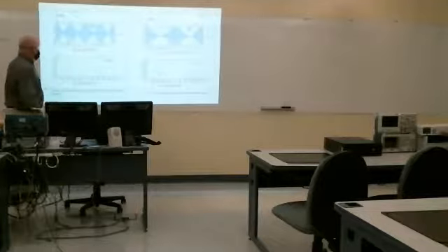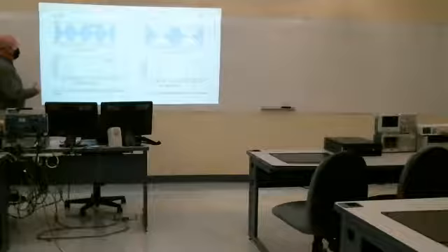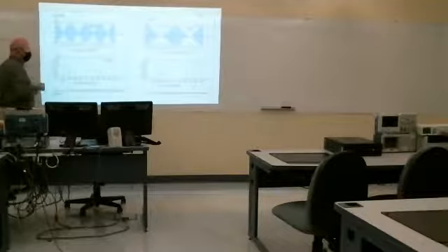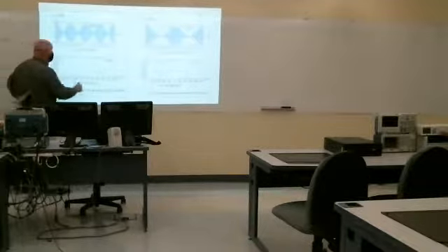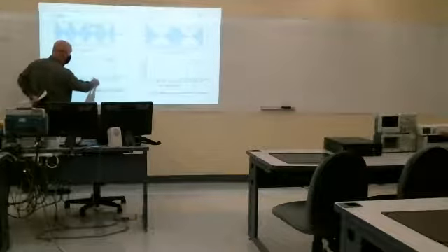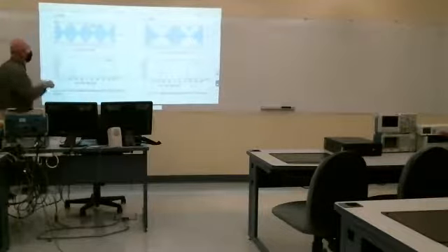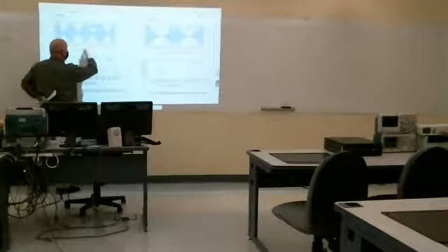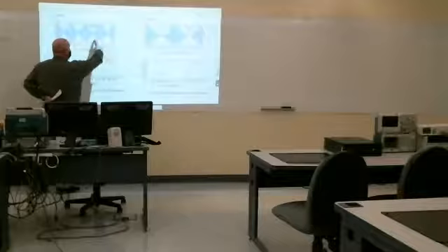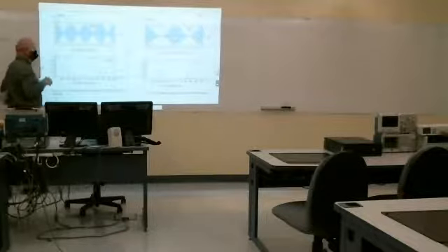You can see that here. This is double sideband modulation of that 1 kilohertz tone. Actually, I guess it's not 1 kilohertz here because they're just modulating to 50 hertz. So if this is really seconds, it looks like it has a period of a second. So it looks like a 1 hertz tone imposed upon a 50 hertz carrier.